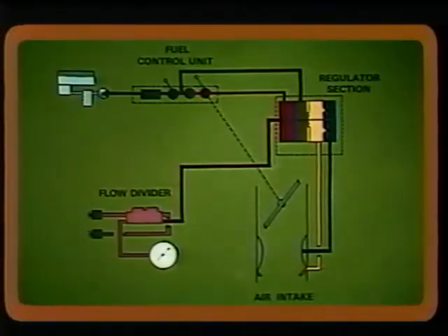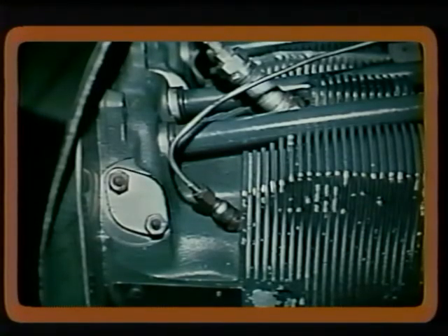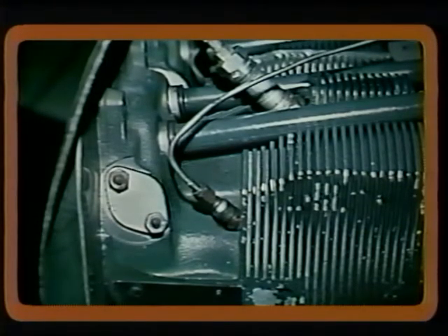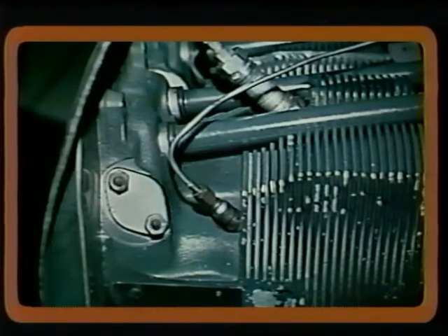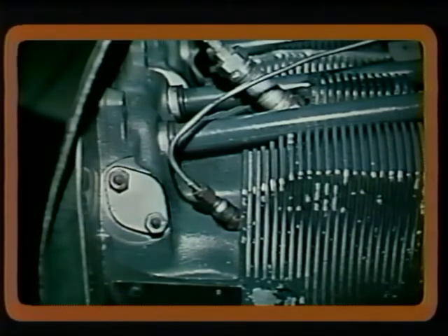These modern systems are very similar in operation to a pressure carburetor because the air entering the engine is measured and fuel under pressure is regulated proportional to this mass of air. This regulated fuel is then metered and distributed to the individual cylinders where it is discharged from the nozzle in a constant flow, just outside the intake valve of the cylinder.